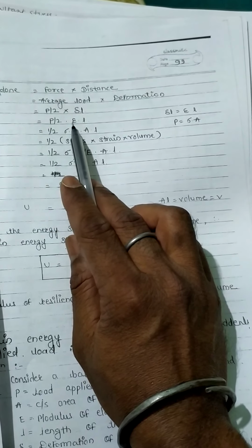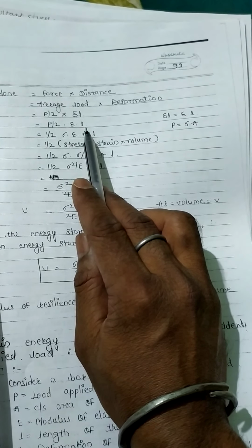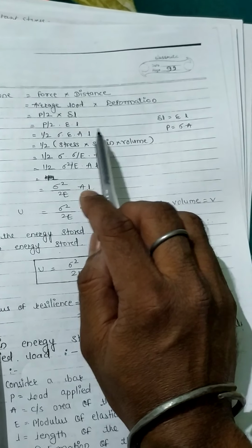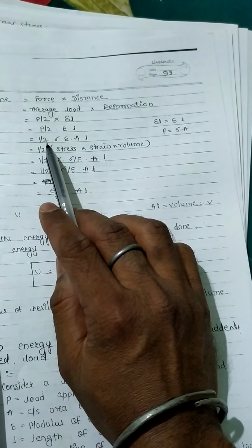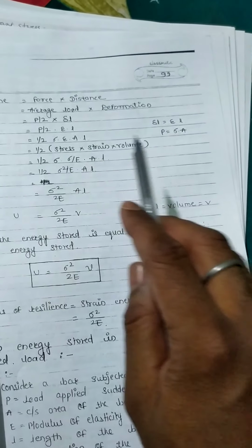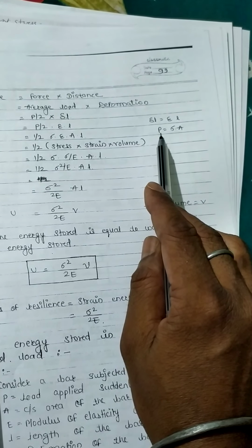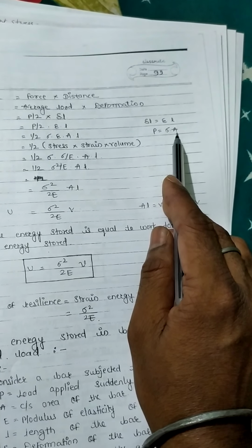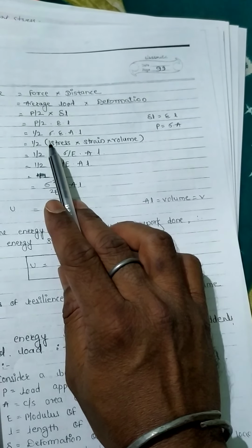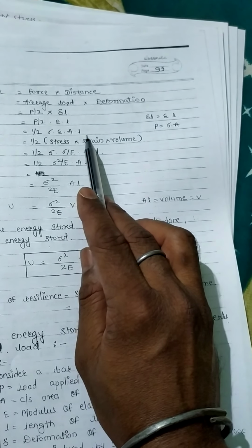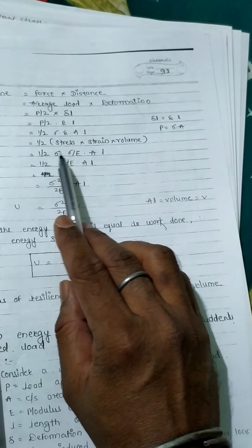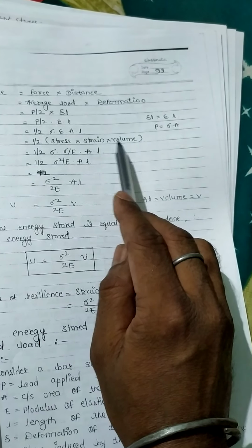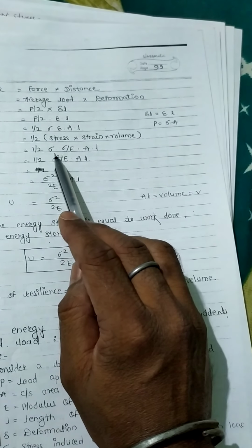So P by 2 into epsilon into L, as strain is nothing but the change in length upon original length. We take another value of P by 2: stress is equal to force, that is load, upon area. So putting this value in this equation, we get 1 by 2 sigma into epsilon into A into L. Here epsilon is the strain and A into L is the volume. So we get 1 by 2 stress,